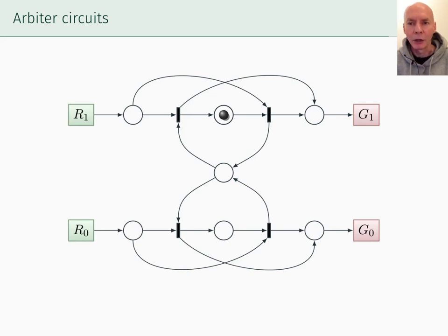Now when the terminal R1 is lowered, the transition R1 fires again, marking the place next to it. These two places along the top enable the other transition to fire, which does so, putting a token back in the middle. Also one next to G1, which fires, indicating that the terminal G1 has gone low. It works the same way along the other terminals.